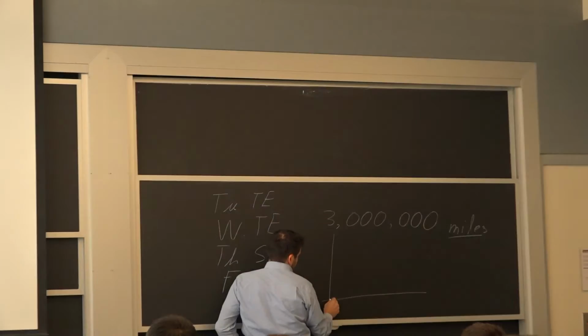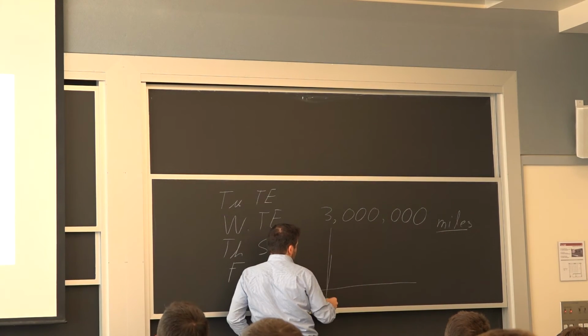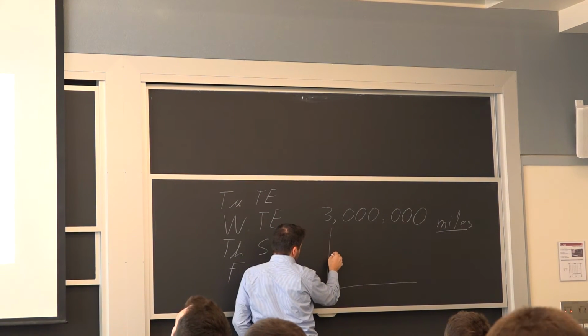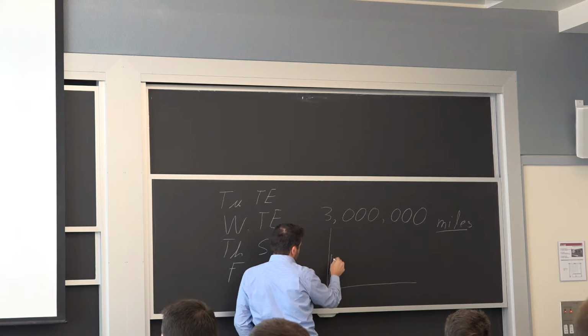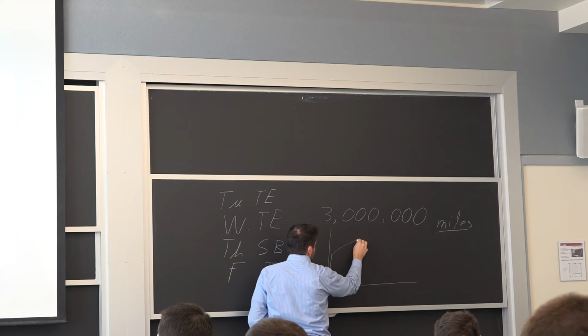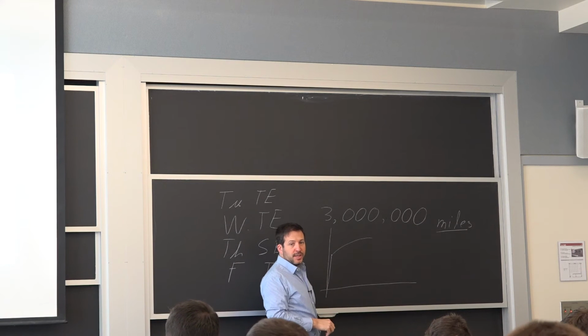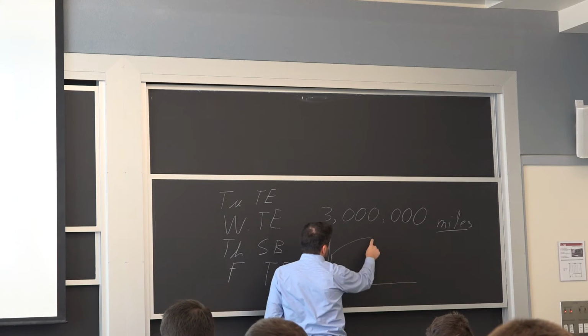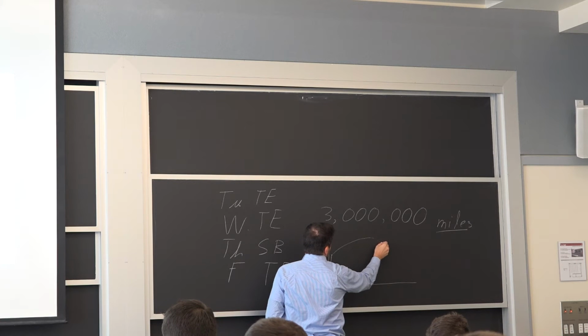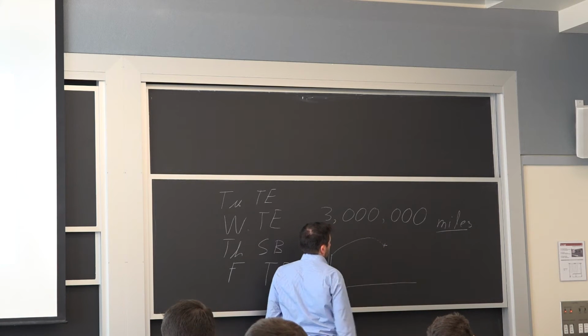So for steel, you have that elastic behavior. It's very, very stiff, so this actually magnifies. Then you have what we call the yield point. It starts deforming. It has a strain hardening. You go through the peak. You have neck formation at that point, so the deformation starts to localize right here. And then eventually it fails, just like that.